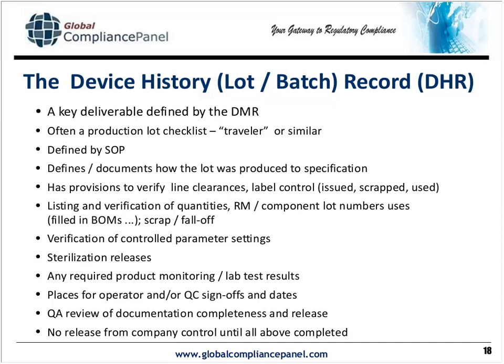And also, if it's sterile and you group several lots of raw material or products into a sterile load, then the sterile load would be part of the device history record, even though it might be a covering document having several batches in it. Certainly you would reference the sterile load number in your traveler for that particular batch. And then maybe have a separate file for that sterile load that shows the result of the test for sterility, et cetera, and the process parameters that were met that had been validated, whether you're using gamma or ETO or whatever.